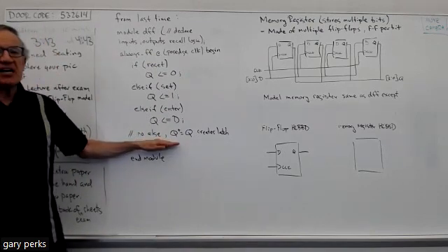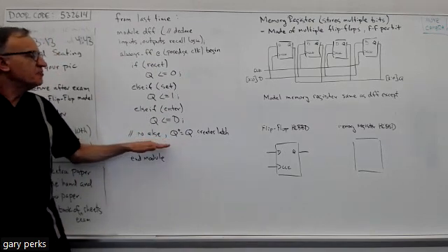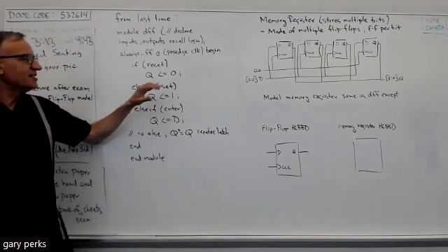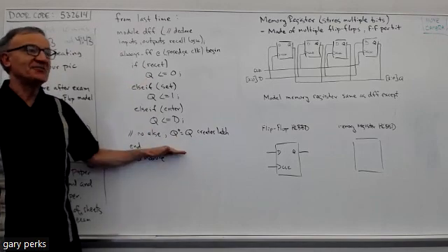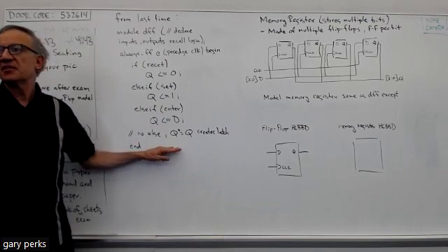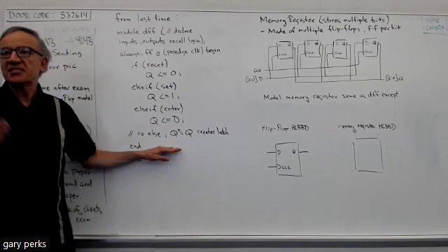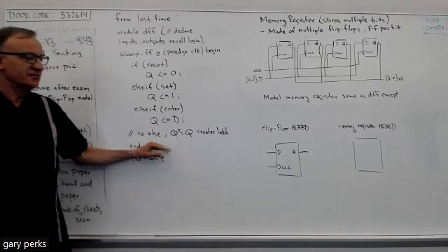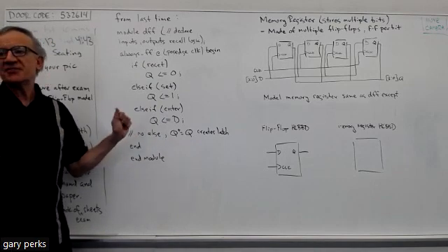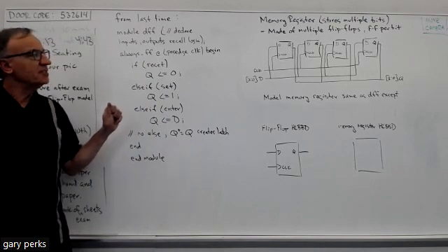Now, when you leave out an else from an if statement, that creates the latch. So if you're not resetting, you're not setting, and you're not entering, you must be saving, where the next state of Q is just going to equal what Q is now. It's going to retain that Q value. Okay, so any questions about the D flip-flop before we move on to a register?